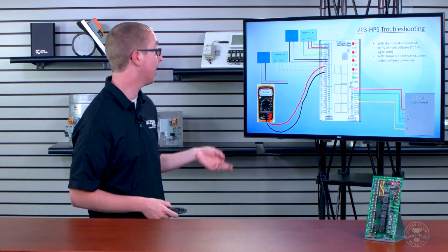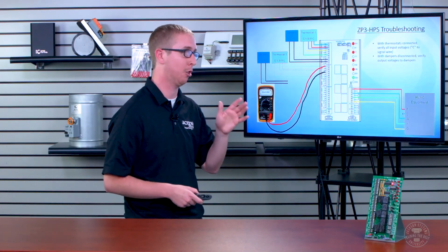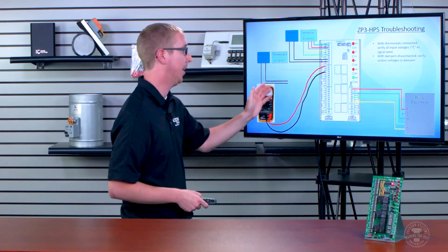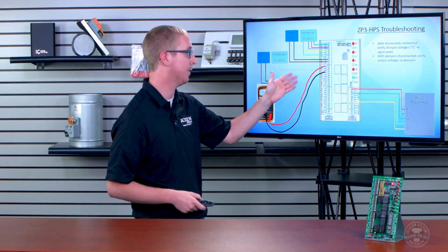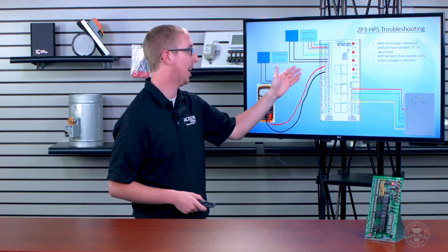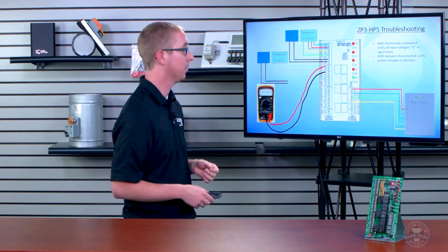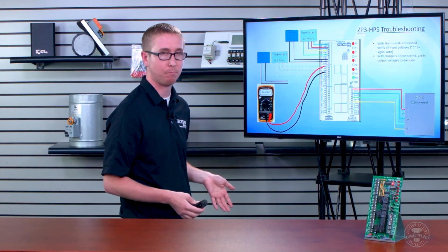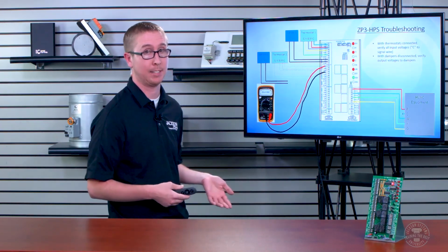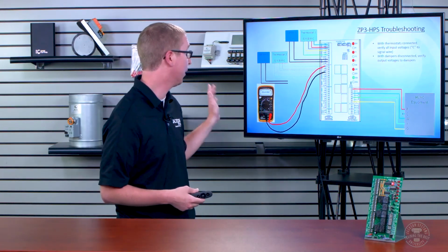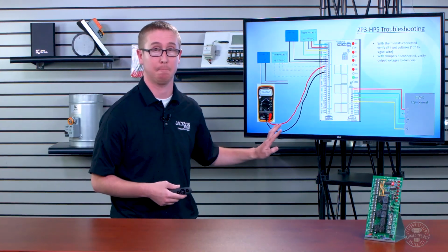But simply said, if you can look at that thermostat and say with 100% confidence, this thermostat thinks it's calling for cooling, and you can go to the zone panel and see that it is not seeing 24 volts between common and Y on its corresponding thermostat terminals, the thermostat never saw the call. So it can't do anything with it if it hasn't seen it yet. That means it is in fact a problem with either the thermostat or the wiring. And the wires could be damaged or it could be miswired.